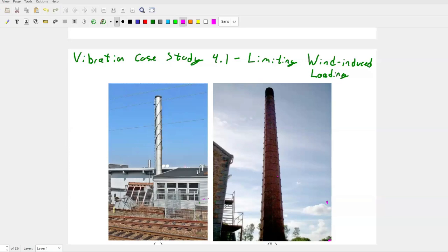So we did that. The smokestacks get higher and they start to fall down, right? And one of the reasons they fall down is if you have something that is of a consistent diameter, you'll start to get oscillating wind currents that form around that, and vortices, right? I'm sure you've seen those videos and pictures of vortices forming.